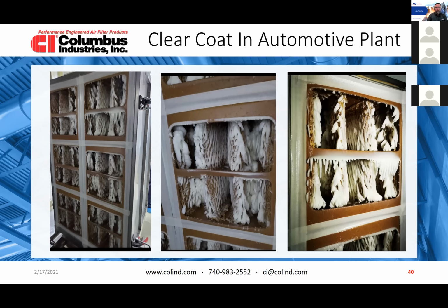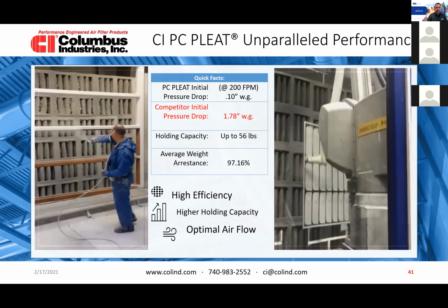And typically these lines will go from, I would say, 8 carts to 64 carts. It depends on how big they are. If they're in the same line doing primer, base coat, and clear coat, that's a big move from the automotive industry. Before, you had to make the primer cure in an oven first and then come back to be painted. Now we're at a process where you do primer and base coat at the same time, and then it cures, and then it goes to the clear coat. So you can see the accumulation of that paint. It's the automotive industry, also any industry really.